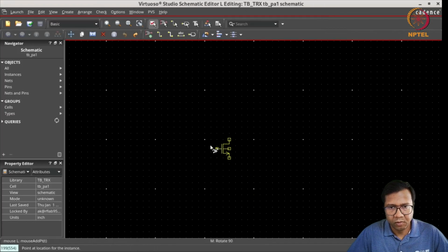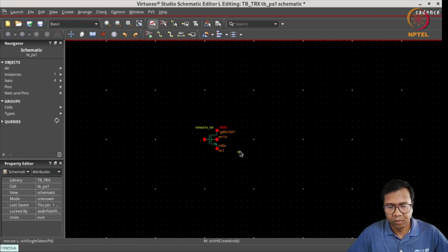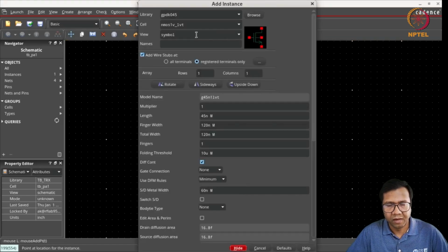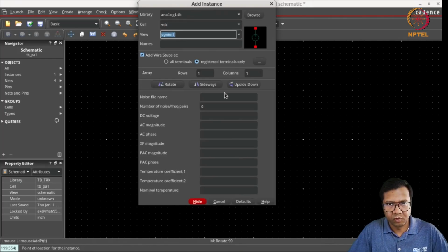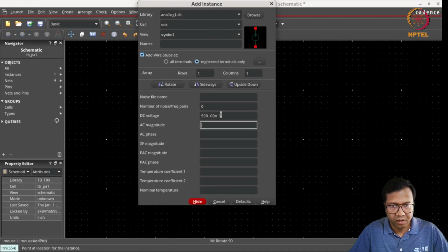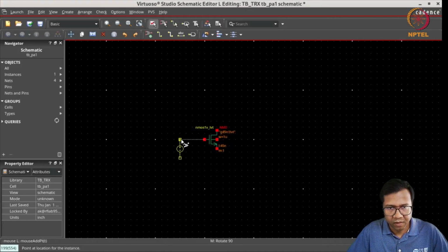So the first objective is to find the optimum gate source voltage for this input element so as to get the best linearity. As we have done for the case of the LNA, here also we are going to choose the gate source voltage such that the MOSFET is operating at the GM3 equal to 0 operating point. Since we have already done the exercise during the LNA design, we know that if we choose the VGS voltage to be equal to 0.59 for this MOSFET, then the GM3 is going to be close to 0 and we can expect good linearity.